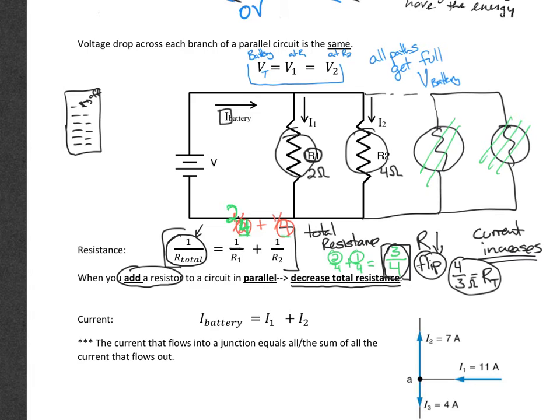Okay, so you write each resistor as a fraction, 1 over, right? Let's clean this up. And let's do that again. I don't want to do the whole problem again, but 1 over 2, because that's the first resistor, plus 1 over 4. Common denominator is 4. And this becomes 2 over 4. 1/2 is the same as 2/4. Now add your fractions by adding your numerators. 2 plus 1 is 3. Check. 4 common denominator, check. Flip your answer, 4/3. 4/3 is really 1.3 if you want to turn it into a decimal. It's called an improper fraction.